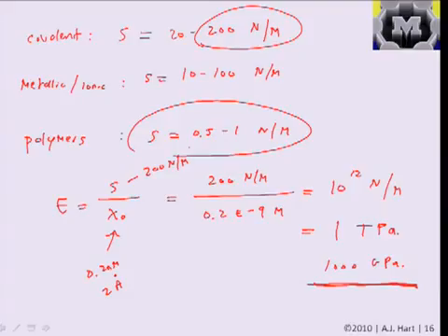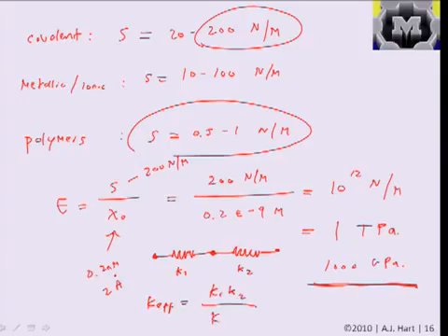So you certainly have that effect, and you also have the effect that in a polymer chain you have different types of bonds. So you might have some carbon-carbon bonds, and you might have some much weaker bonds like, say, carbon-hydrogen bonds. And if you think of a material as a chain of springs, then the weakest bonds are going to dominate. So if you think back to, say, 3 atoms in series, and we had 2 different bond stiffnesses, and we derived the effective stiffness of this series combination of springs, then we would see that this is equal to K1 K2 divided by K1 plus K2. And then, if K1 is much less than K2, then the K2 goes away from the bottom, the K2s cancel, and this gets to K1.